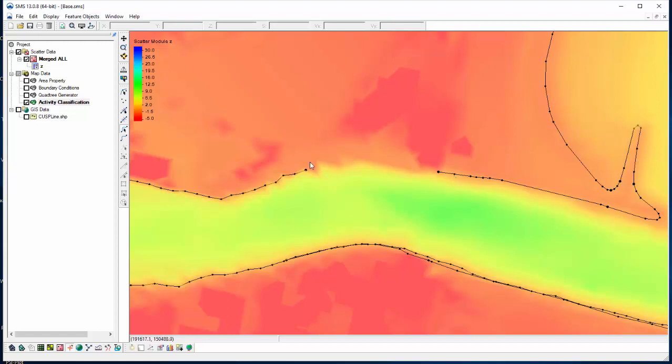We've got a gap, and we have the rest where we brought it in from our contours. And we can just connect that with the Create Arc tool. And I'll just connect this up and follow the shoreline. Double click on the end, and now we've got one long arc that basically represents everything we want.